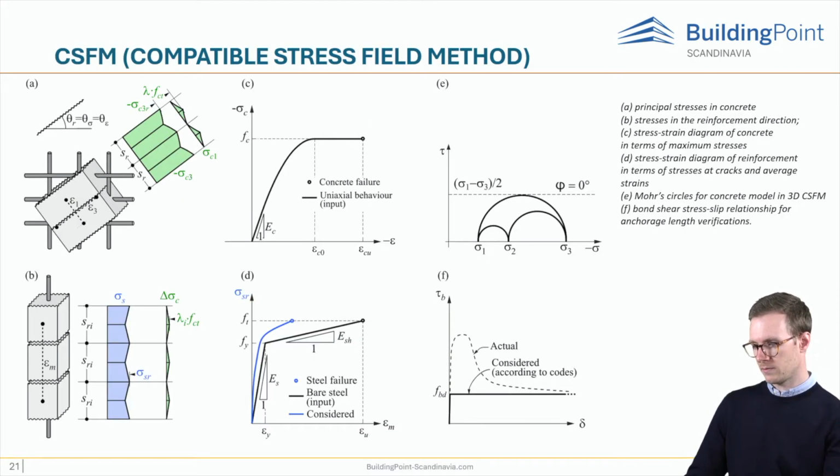Further on, this 3D CSFM method defines the concrete behavior based on the modified Mohr-Coulomb plasticity theory for monotonic loading. The method considers principal concrete stresses in compression and reinforcement stresses at the cracks while neglecting the concrete tensile strength, except for its stiffening effect on the reinforcement.